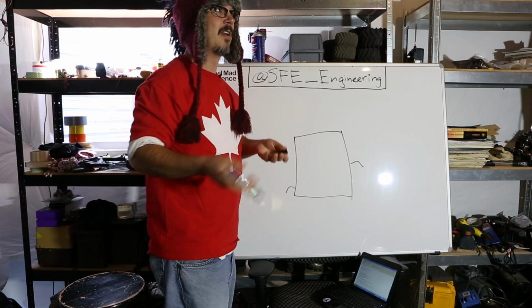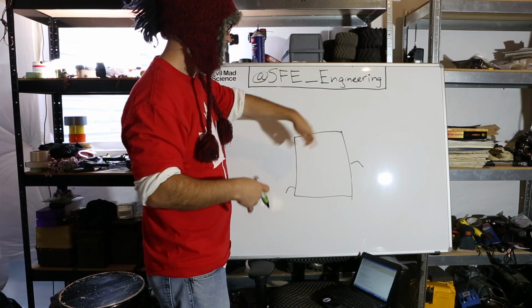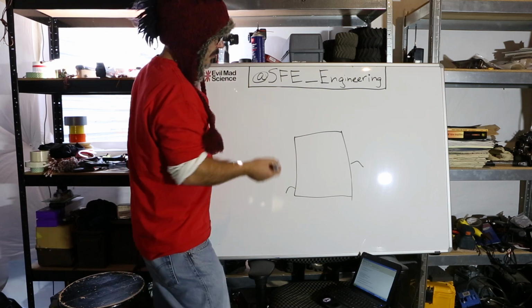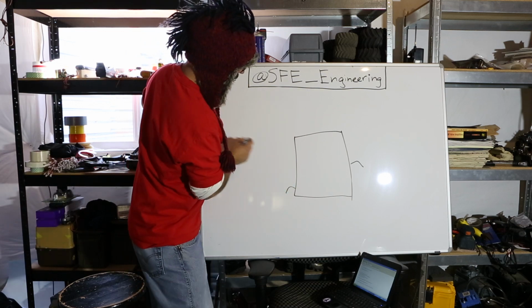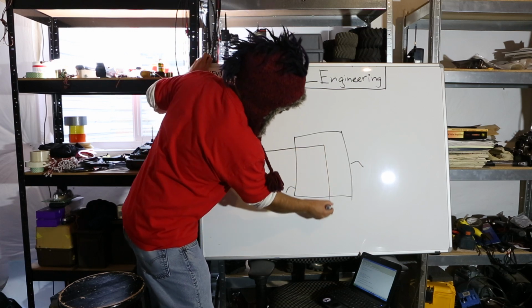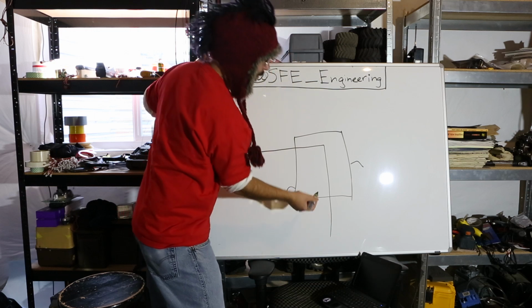And I've had to do this on a few Analog Devices parts. They're big on doing that. They've got a digital front end to something that's got an analog input. And so what they say is, okay, we want you to run a ground plane that looks like this, and picture this running under the part, right? And they may specify this or they may not.